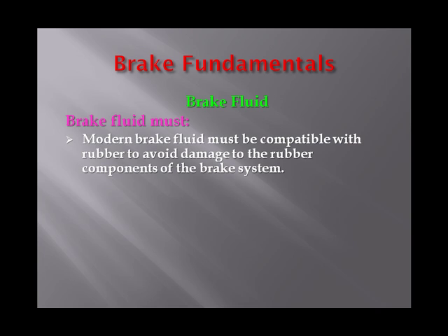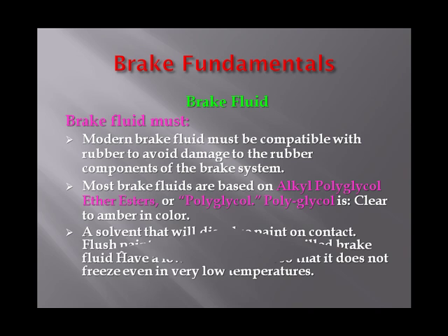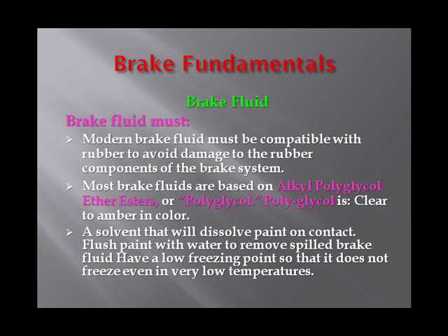Modern brake fluid must be compatible with rubber to avoid damage to rubber components within the braking system. Most brake fluids are based on polyglycol or ether esters. Polyglycol is clear to amber in color. It is a solvent that will dissipate paint on contact. Flush paint with water to remove spilled brake fluid.